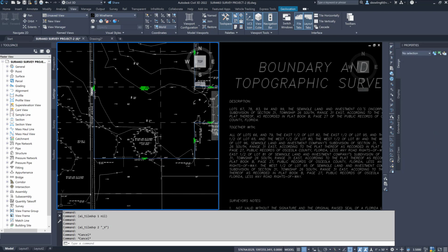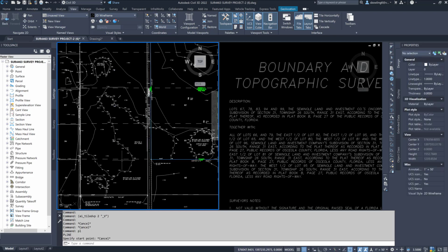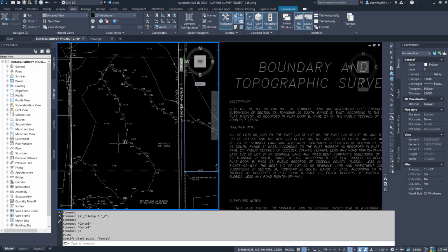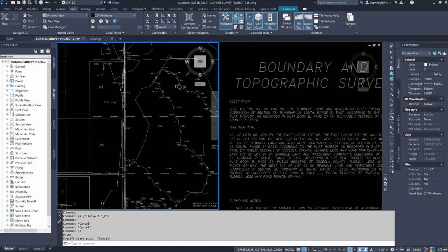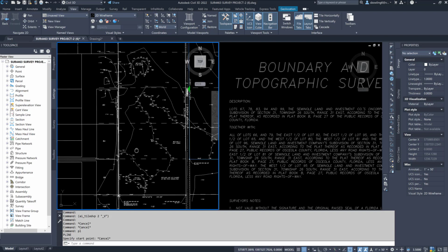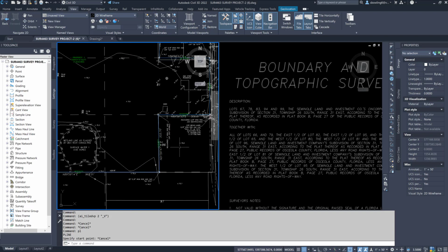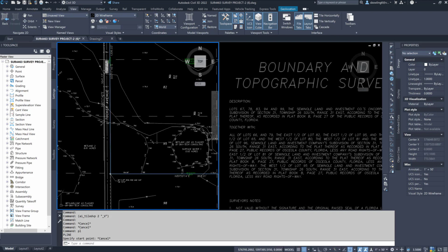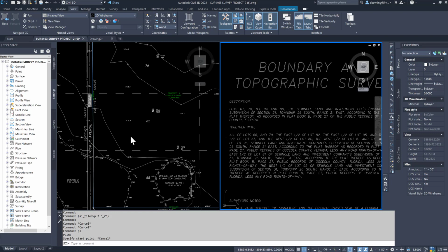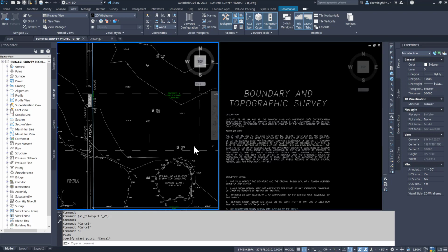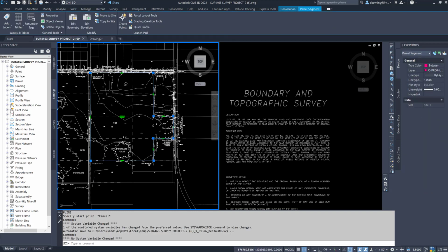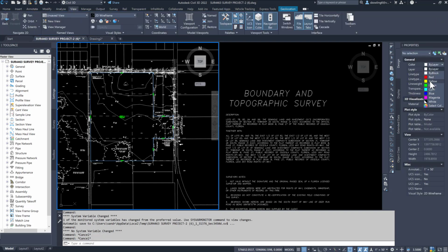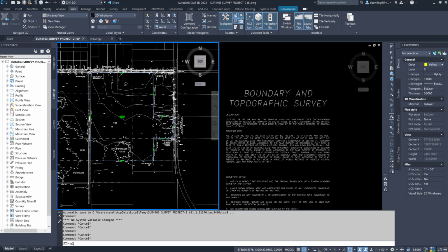And again, east half of lot 95. Because if this is an entire lot here, there's 94, and here's 94, there is something off on their legal description, okay? Because this is showing the entire lot 95 in, the entire lot of 82 in. So my guess is this legal description on this side was originally half of that. So it would have been a, and let me just get a color. We're going to do yellow. If they were saying that it was midpoint,